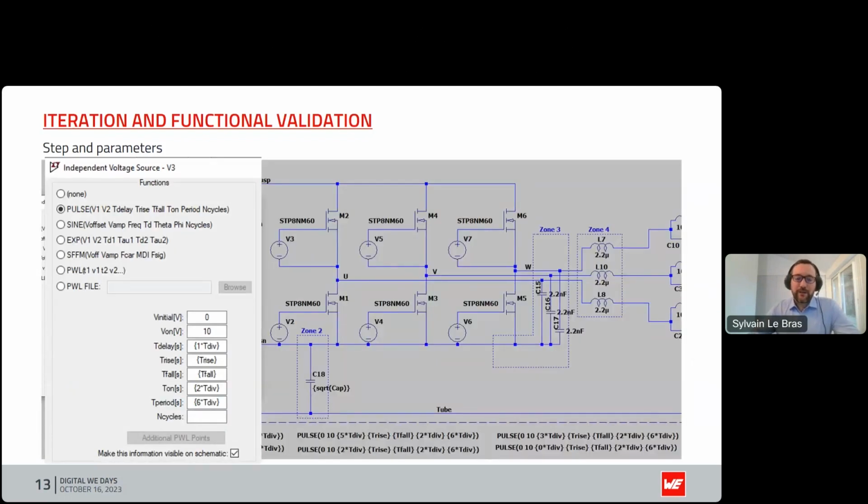So here is an example of what I'm doing with the parameters. I'm generating with these parameters the signals that will be used for driving the MOSFETs. For example, as you can see, I'm using here the TDiv, T-rise, and T-fall, and here again the TDiv. And here the location of the on time and the period are changed by using the relationship between these.